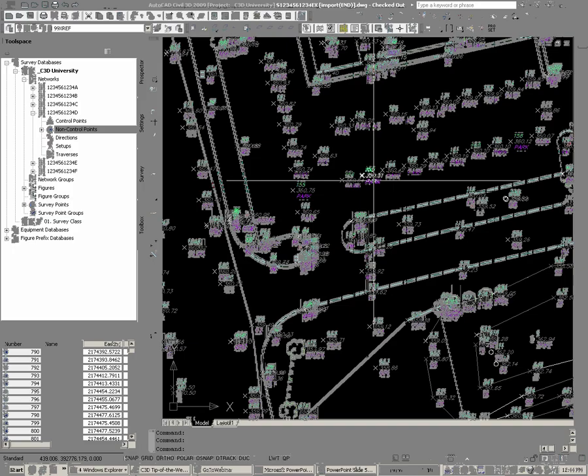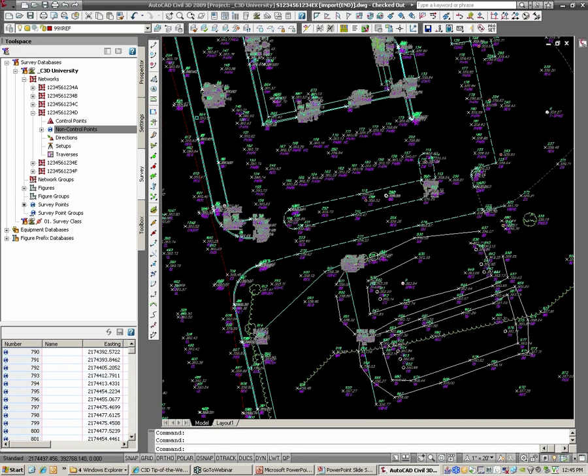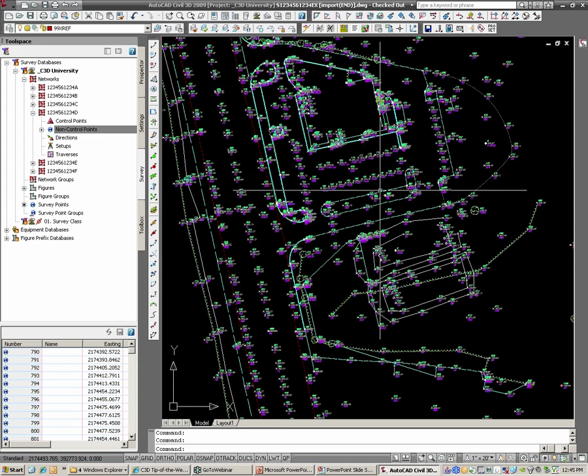based on the points. If there were break lines and other things involved, I'd have to go ahead and manipulate those. And of course, if I had this full-fledged design on the project, there would be a lot of rework adjusting those profiles. Of course, all your profiles would update when the surface raised, but you'd still have to update your design to match. So that's how you can translate and rotate and raise and lower points.